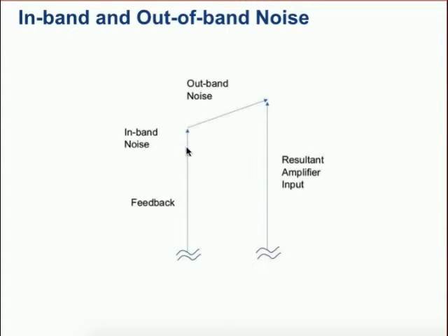Now also we've split the noise up into two components, the in-band noise and the out-of-band noise. Actually there's not a completely clear distinction, but noise that's well inside the oscillator bandwidth is processed differently to noise at a higher frequency offset. So first of all, let's consider what happens to noise well inside the oscillator bandwidth, and by the oscillator bandwidth we're talking about the bandwidth of the resonator, which has been vastly reduced by the effect of positive feedback.